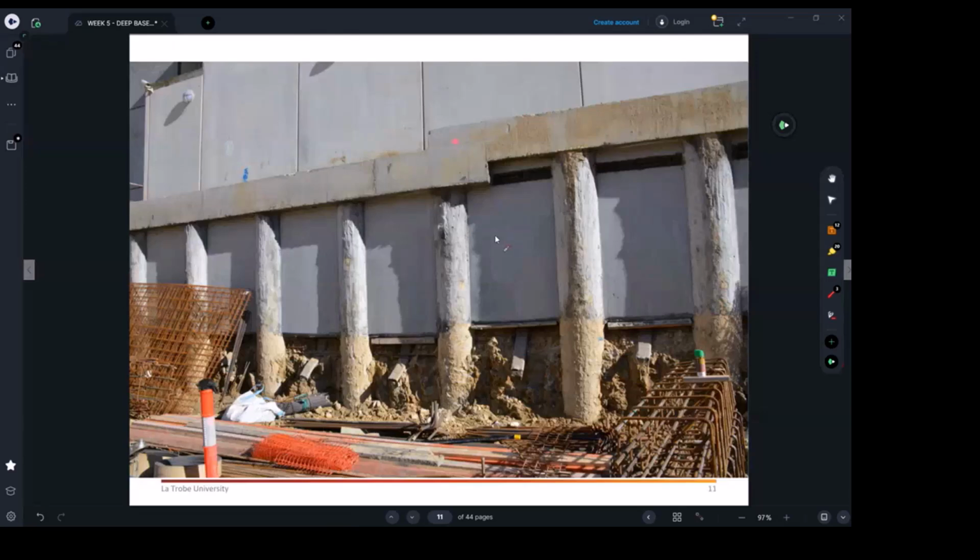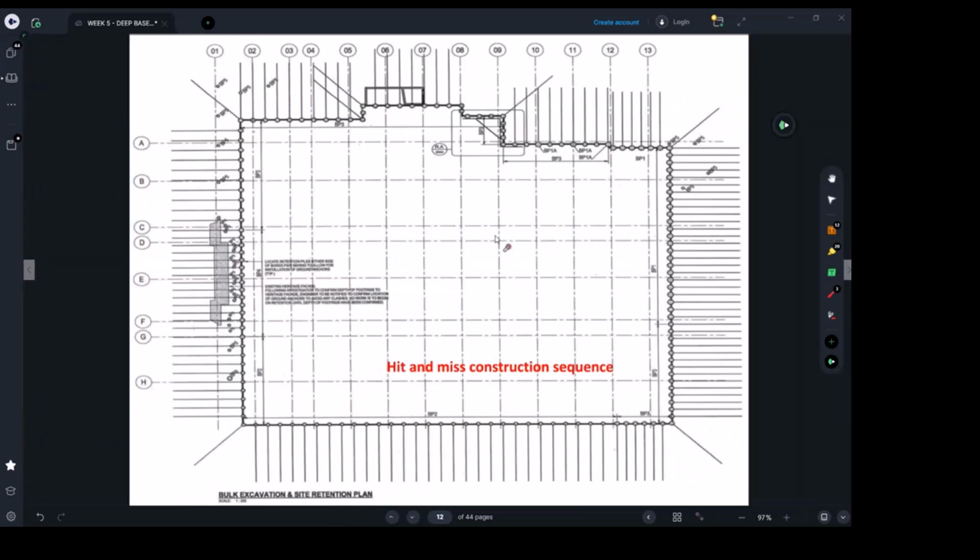But one thing I want to tell you, in some projects you don't need to do that, in others you do need, depends on what's really in the ground below the basement. Do you have a lot of rock that you can't excavate through? Then we're just going to go 1 meter and stop it there and use anchors. If you have a softer kind of soil, you can go easily 9 meters into it. So that's fine. Go in. You don't need to put anchors. And we will show you both examples.